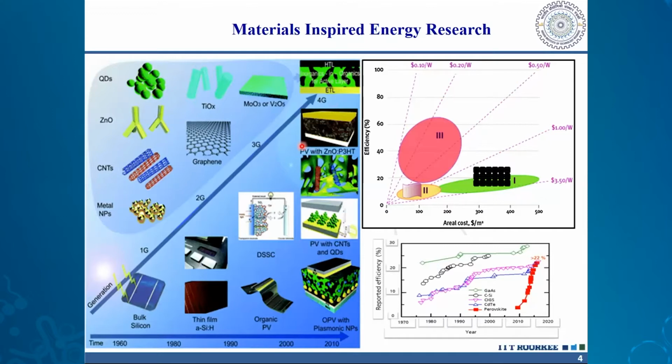Now, the major difference between the different generations of solar cells is the cost and the efficiency. As you can see, the first generation silicon solar cells often show a very high efficiency, but they also come with a very large cost. Since a technology will be viable only if the cost and efficiency circle, or the triangle, is optimized, there is a continuous surge of research to discover new materials for finding low cost and high efficiency solar cell devices.